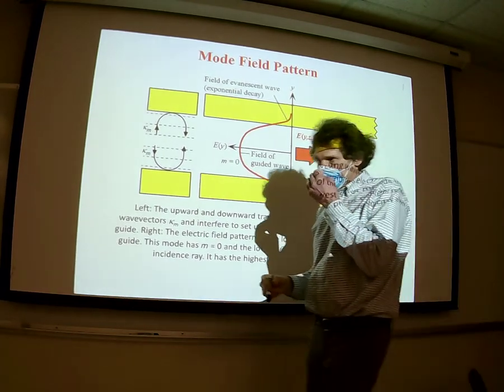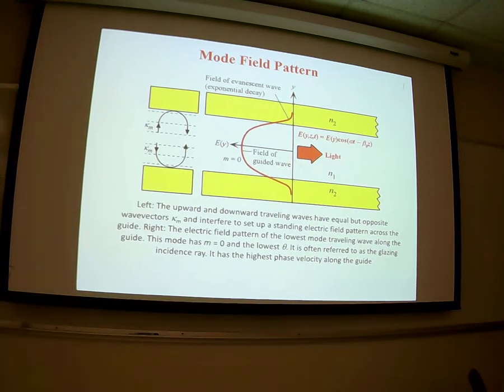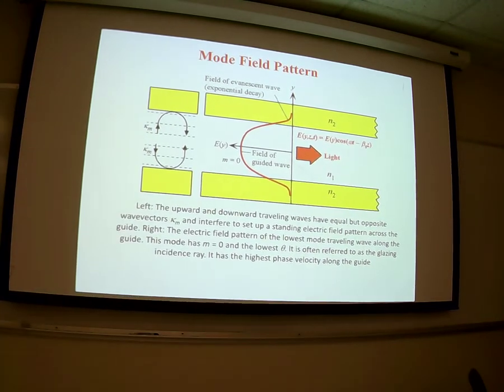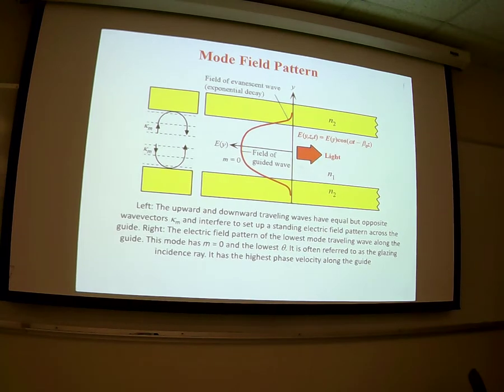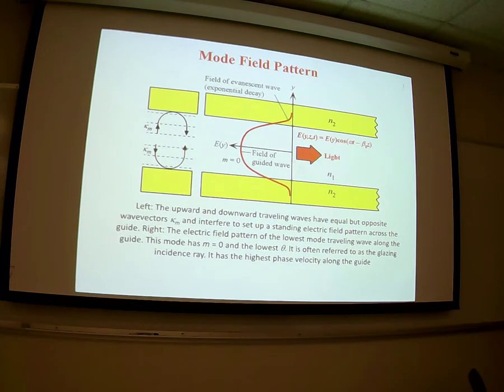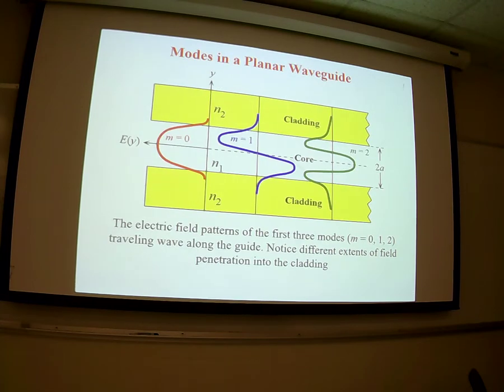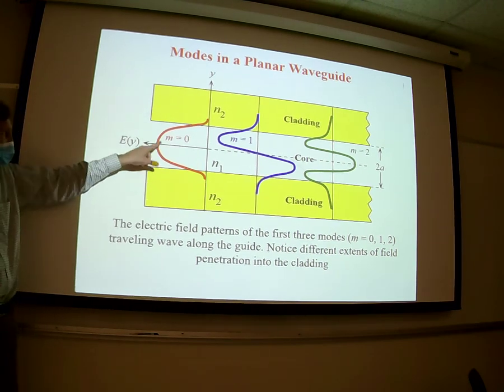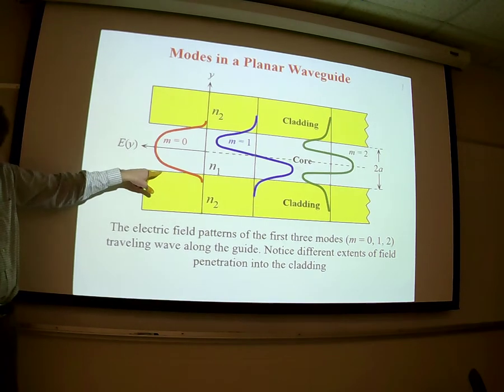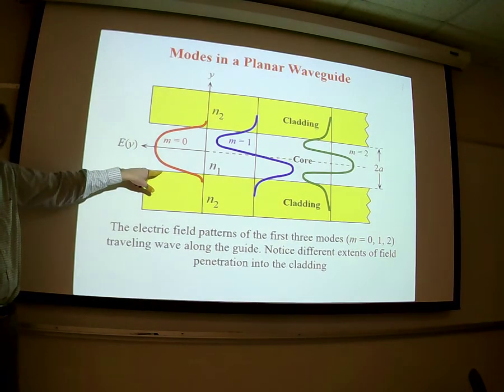Now, that's a lot of trouble, but the solutions require you to do something where you get transcendental solutions, and hopefully I can explain this without scaring you. Now y'all see what's going on here. Here he shows the zero mode. That's a half wavelength. Do y'all see that? That's the first figure right here. The frequency associated with a half wavelength here to here is the zero mode. That's the lowest order mode that propagates.